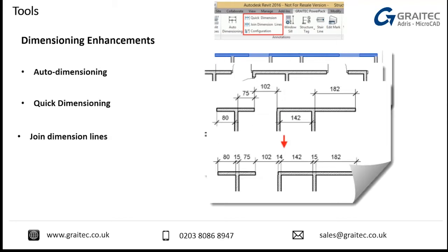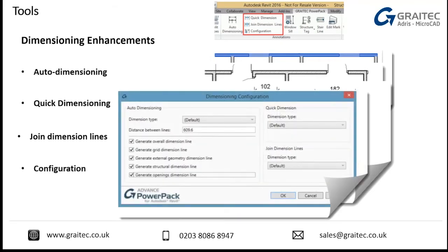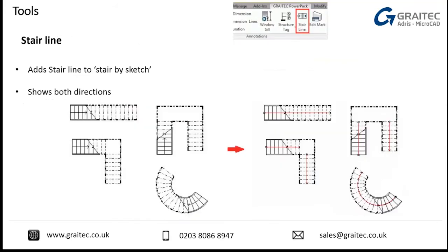We can join dimensions, so if we've got dimensions that have been drawn multiple times, we can join them into an entire string, which is editable afterwards. We can also configure this, so we've got a configuration tool in there which gives us control over which dimension style and what font. We might have multiple different dimension styles, but when it comes to auto dimensioning, which dimension style is it that we actually want? We can change that between the auto dimension, the quick dimension, and the join dimension, so you can have different styles for each as well.